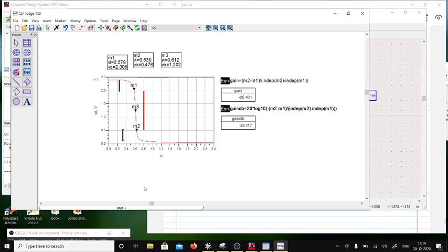Right, and this voltage will cause the NMOS device to go into the triode region. So you will lose all the gain because the RDS has gone. So basically your useful gain is only between VDD minus V overdrive and V overdrive.